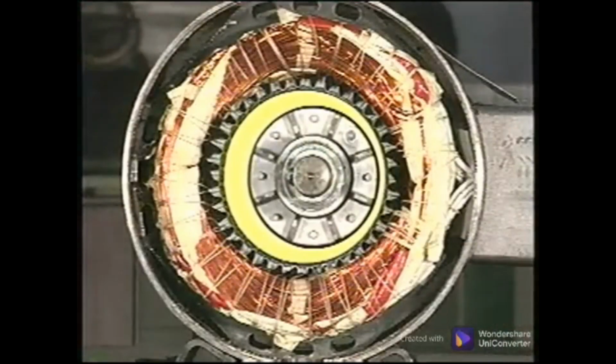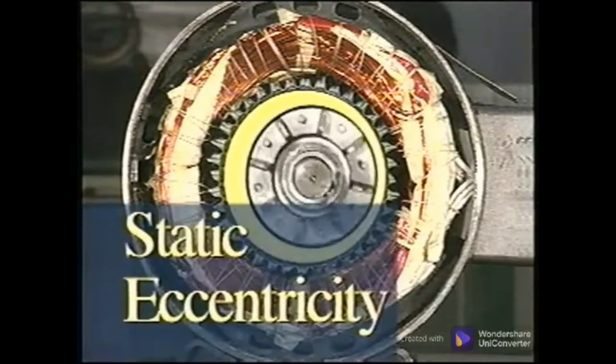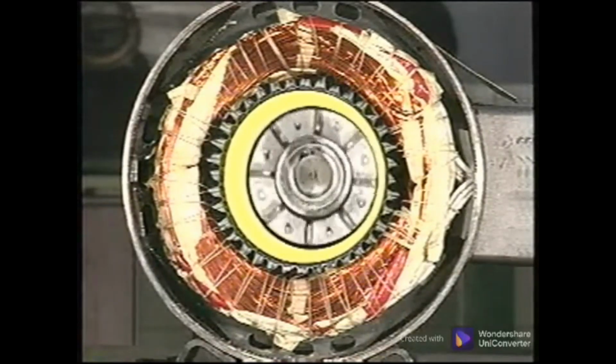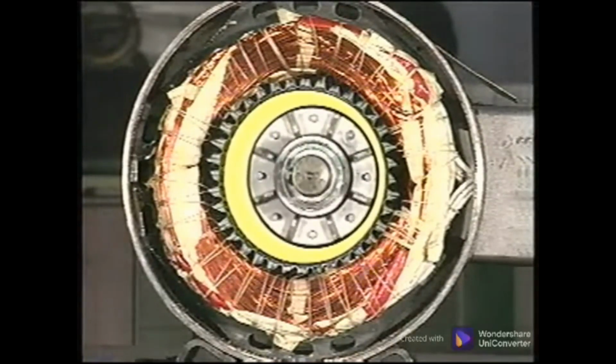Another eccentric air gap condition can exist, and it is static eccentricity. Static eccentricity is a condition when the air gap is eccentric, but it stays in the same position. This can result from 2 causes. One is that the center line of a perfectly round rotor is not in line with the center line of a perfectly round stator, or it is off-centered.